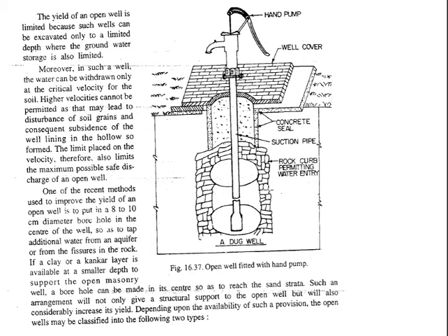The yield of certain types of open well is limited because such wells can be excavated only to a very limited depth. We don't go very far down. Obviously, if it is limited to a very shallow depth, then its storage will also be limited. In order to enhance the storage in this type of well, they are mainly preferred in areas where the water table is quite high, so that if the walls are permeable, the water can come inside and enhance its water capacity, or the volume of water stored in it.